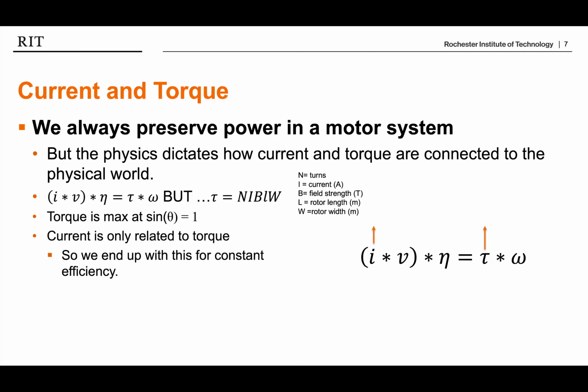maximum torque. Now, I'll run through that one more time because this is a really nice, important concept to have. So I would write this one down. Motors will demand current to try and get the highest torque at a given RPM. Once you reach that point, giving a motor more current will not produce more torque. So there is a maximum here. There is a maximum torque at any given RPM.